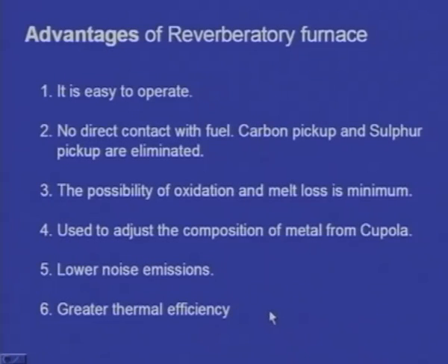Advantages of the reverberatory furnace: it is easy to operate, no direct contact with the fuel. We have seen we are not heating the metallic charge directly with the fuel. The hot gases are heating the furnace roof and the walls, and the heat reflected and radiated from the roof and the walls are coming and heating the charge.